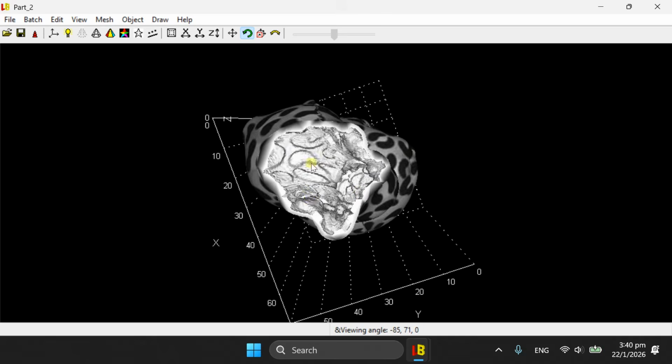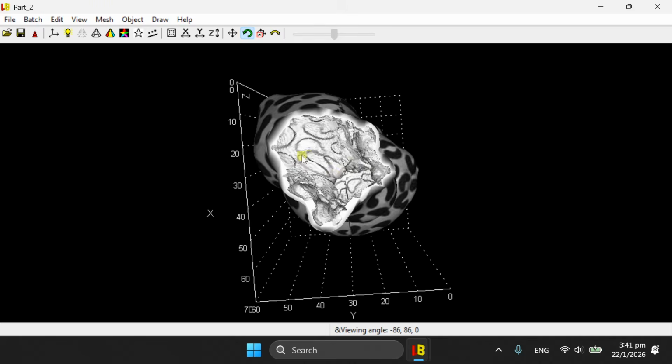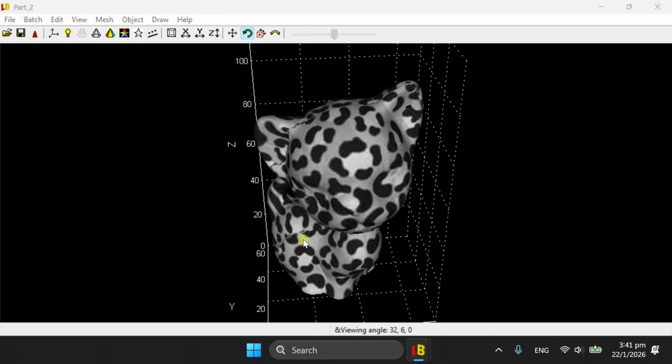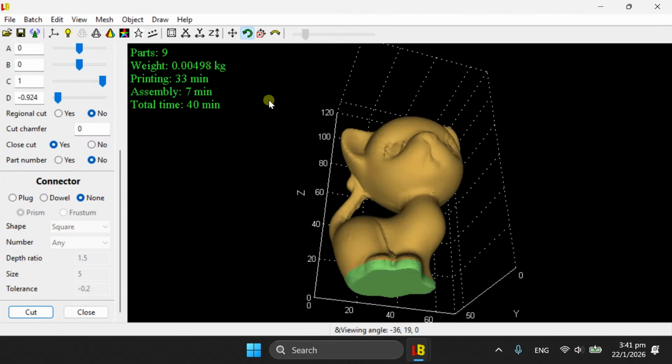I believe the last setting was internal lithophane, so the surface variation was generated on the inside. An external lithophane would be better. An external lithophane will be more clear. An internal lithophane is only for special applications where you have some kind of silver gray PLA. Only when that is the case, you have a clear internal lithophane. Otherwise, it's a bit blurry.